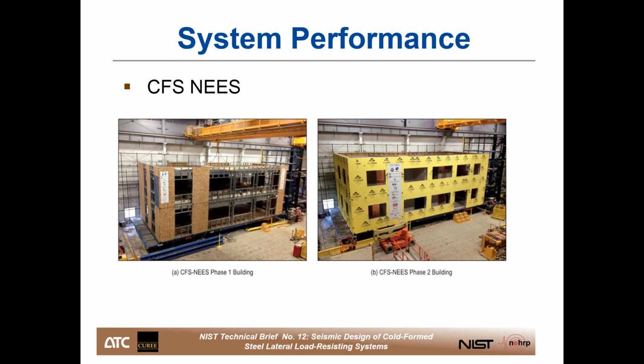So full-scale testing included multiple phases. And in phase 1, the building was shake table tested with just the design structural system. So like on the picture on the left, you can see the framing is there, and there's just some OSB shear walls along the length of the walls and in a few of the corners.